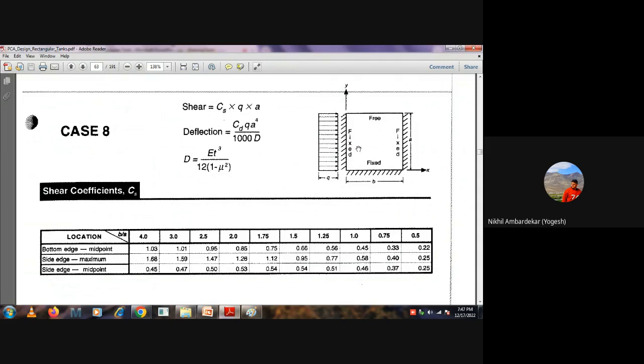And is it fine to reduce the wall thickness at the side compared to the bottom? No. You will provide uniform wall thickness, correct? Yes, sir. So if you calculate the 1.4 into 74, that is somewhere side maximum. So the same thickness you need to provide everywhere, correct? That's why we have to consider maximum.